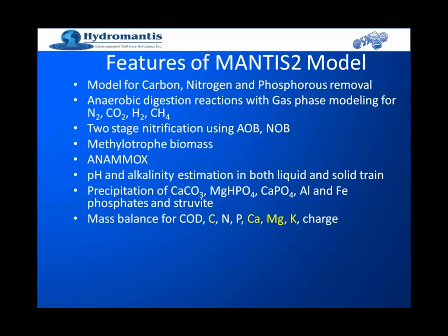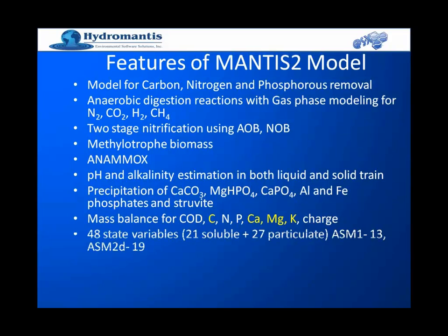Of course, we do the mass balancing in this system for COD, and we have extended the balance to include the carbon to model the pH in the systems, also nitrogen and phosphorus, and we have extended the balance to include calcium, magnesium, and potassium in the model.